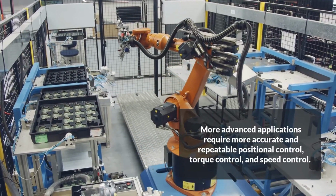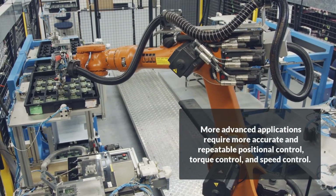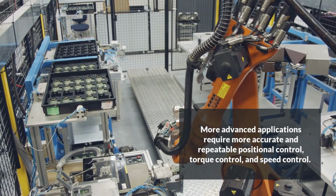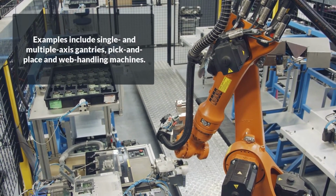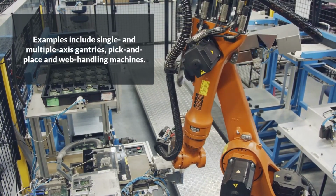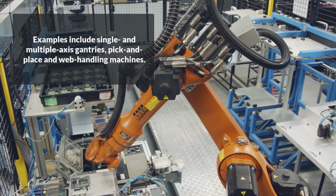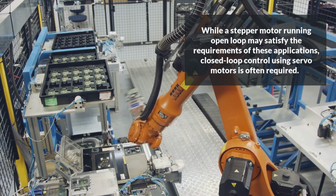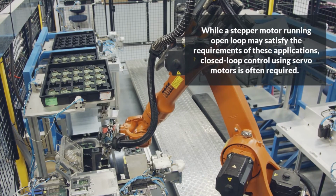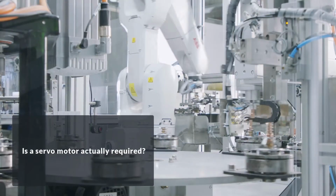More advanced motor applications require accurate and repeatable positional control, torque control, and speed control. These applications include single and multiple axis gantries, pick and place, and web handling machines. While a stepper motor running open loop may satisfy the requirements of these applications, closed loop control using servo motors is often required. Do you really need a servo motor?